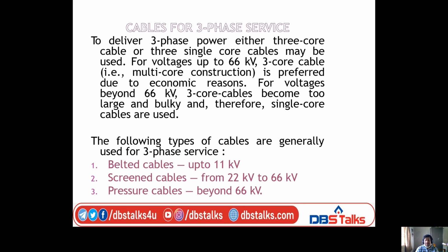Now we go for the cables for three-phase service. To deliver three-phase power, either a three-core cable or three single-core cables may be utilized. For single-phase supply, we are utilizing single-core only. But to deliver three-phase power, we are utilizing three-core cables, otherwise three single-core cables. For voltages up to 66 kV, three-core cable or multi-core construction is preferred for economic reasons.